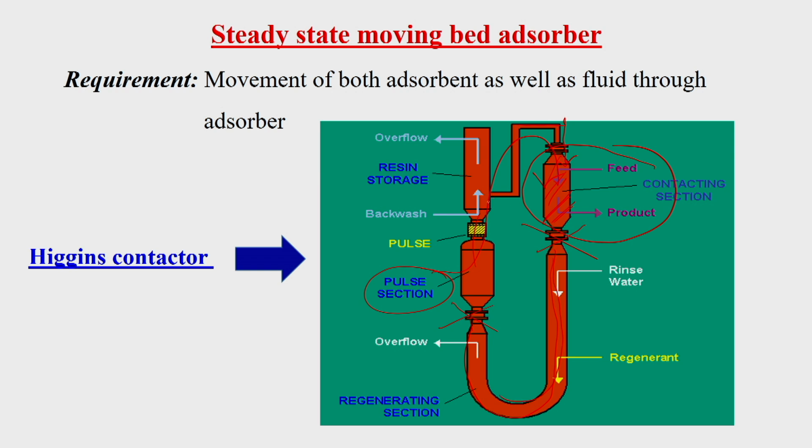If we just pressurize the system, whatever adsorbed material came from the previous operation will enter, and then some regenerants are added along with some rinse water, and this overflow is used to separate the target component or adsorbate. So, through overflow the adsorbate is separated during this regeneration process. The regeneration process, temperature swing or concentration swing, we will discuss in the next class.